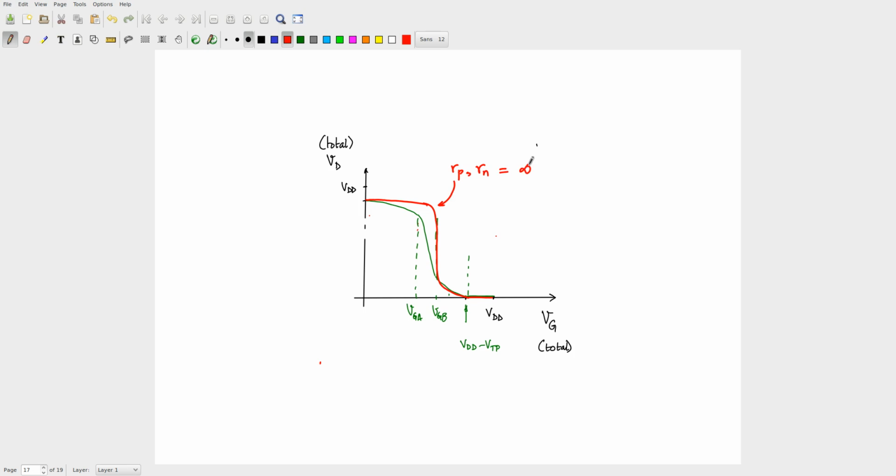Okay. So in your digital circuits class, where did you bias or where did you operate your inverter? Right. So for your digital circuits class, I am going to draw things in yellow. So you operated in either that region or this region. If you want to use the same circuit as an amplifier, where will you operate it? In that circuit. Correct. So the same circuit can operate either in a digital logic, where you only want the level and are not interested in any amplification, or as an analog amplifier, where you want amplification. So the same circuit will work for both.